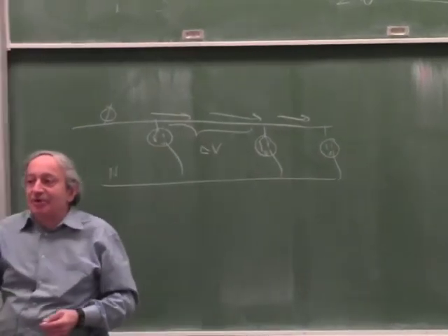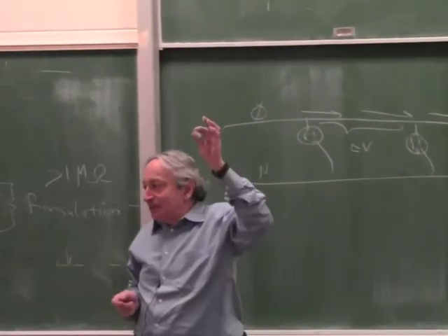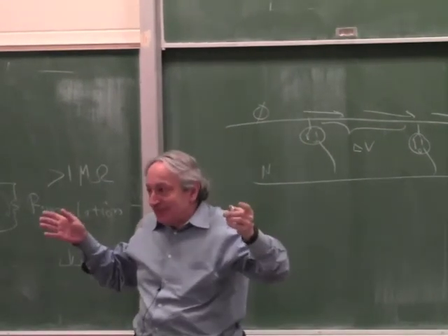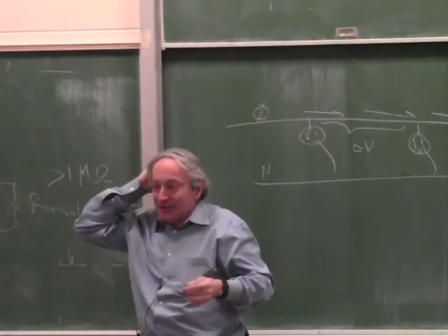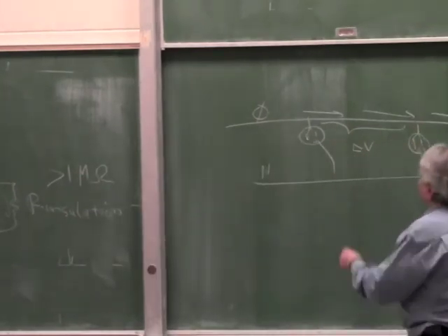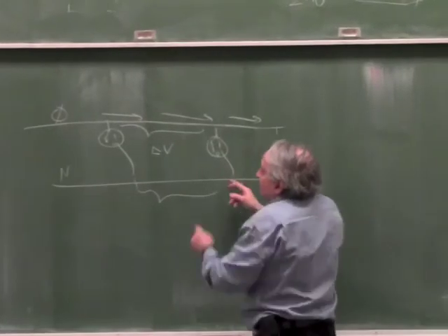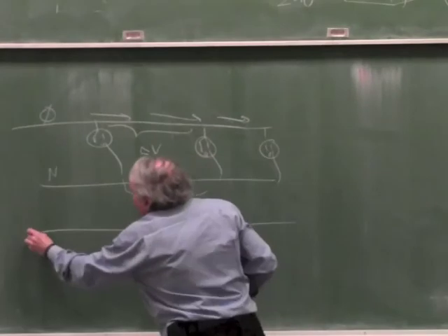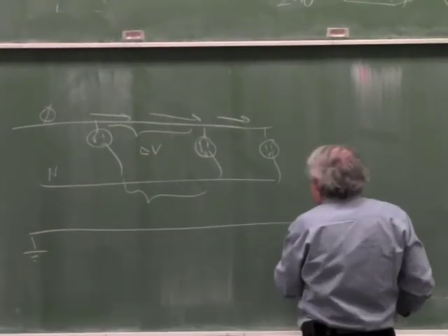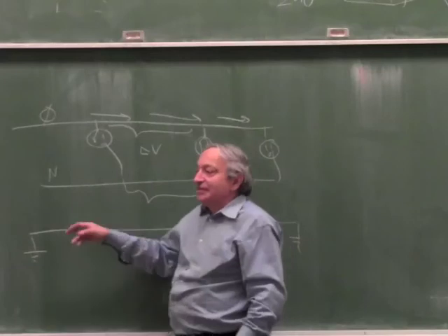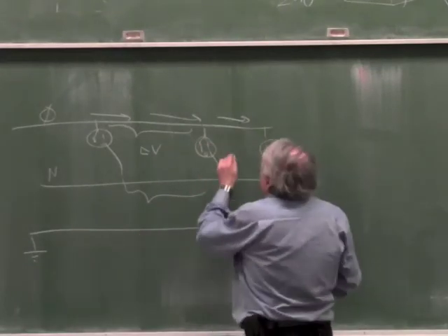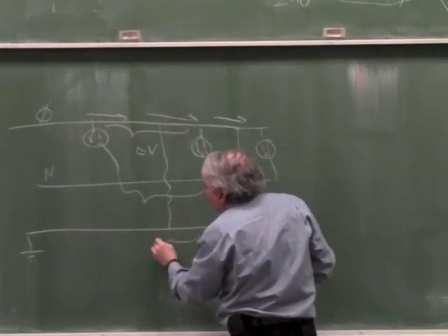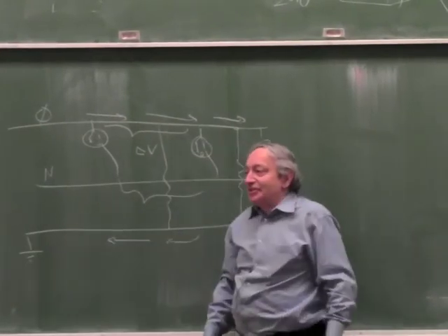And the best example: when you turn on your toaster, the lights dim. Especially in old houses, lights dim, which means there must be a delta V. Right? 10 volts at least. So I expect delta V between outlets, and I expect delta V between neutrals, because it's the same as a phase, the same wire. But I didn't expect that the ground, which is supposed to be 0 volts, also has little delta V's along it because of leakages. There are all kinds of leakages to the ground which cause small currents to flow through the ground.